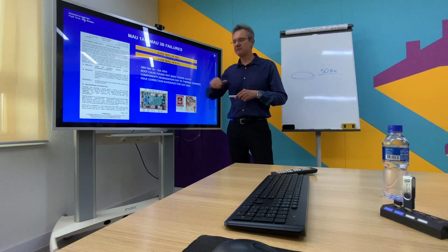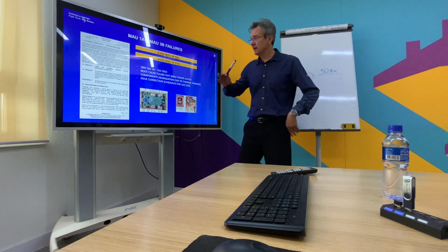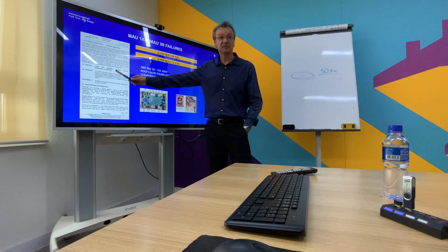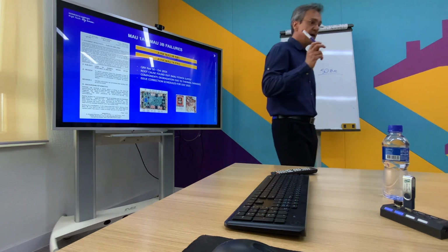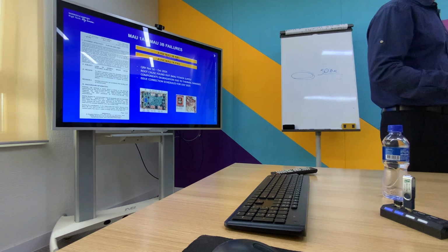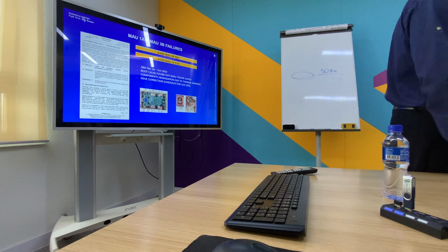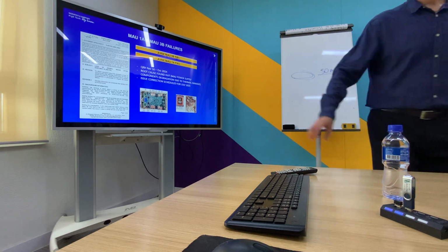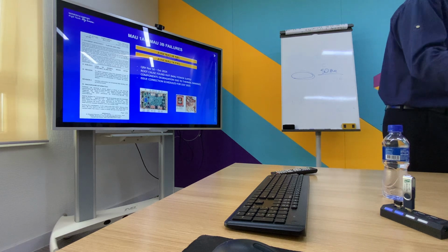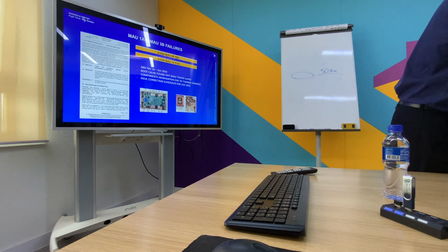But we are facing this situation, and I do recommend there is an OB regarding this failure, since sometimes we may use the parking brake to land the airplane because you're going to lose brakes, so as not to keep the airplane on the runway. This OB states a procedure to recover half of the brakes so as to allow you to go to the gate.